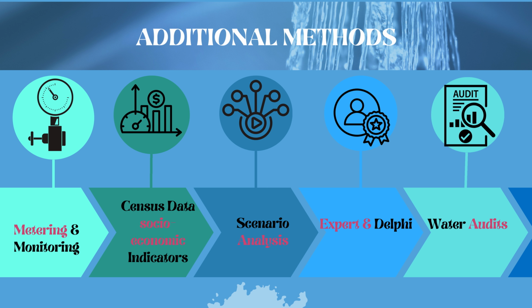Scenario analysis: this method involves creating different what-if scenarios, like a population increase or climate change, to see how water demand might be affected. Also, the expert and Delphi method means consulting with experienced water professionals and using techniques like the Delphi, which means gathering expert opinion without knowing individual names. This can provide valuable insight into water demand assessment.